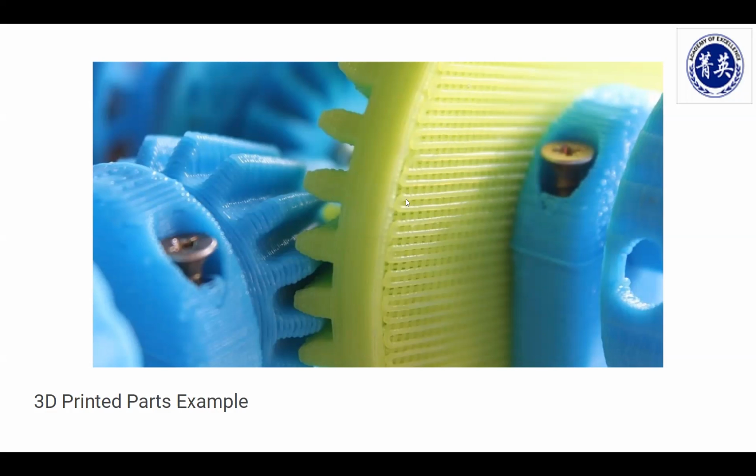So to design something to be 3D printed, sometimes you have to increase the tolerance of the parts, meaning make the gap a little bigger, right? The mating surfaces, if the actual metal or plastic part is made out of actual material or by injection molding, the tolerances could be a little bit tighter than what 3D printed material can be. You can see the gap in there, two gears here, the blue gear and the green gear. The gap is actually rather significant because for the 3D printed material to work, it has to be big because the surfaces are not clean.